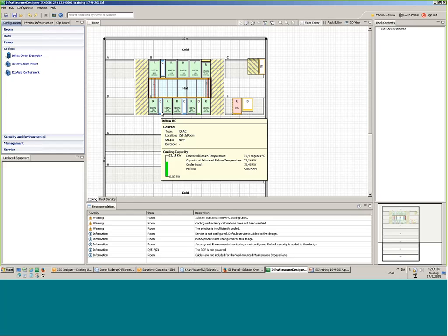Yeah. So that's the one I wanted to show about the cooling. Then if I go to the rack, right now, maybe you see it, I have 125 CFM. That means that I have a delta T of 14 degrees over the server. And this is also why, if you look, for example, in the